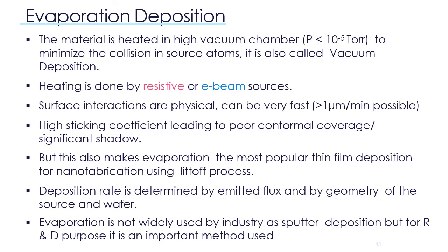Okay, so this heating process is performed by a resistive or e-beam source. That's why we give the names thermal evaporation and e-beam evaporation. The surface interactions are physical and it can be very fast, at around bigger than 1 micrometer per minute.